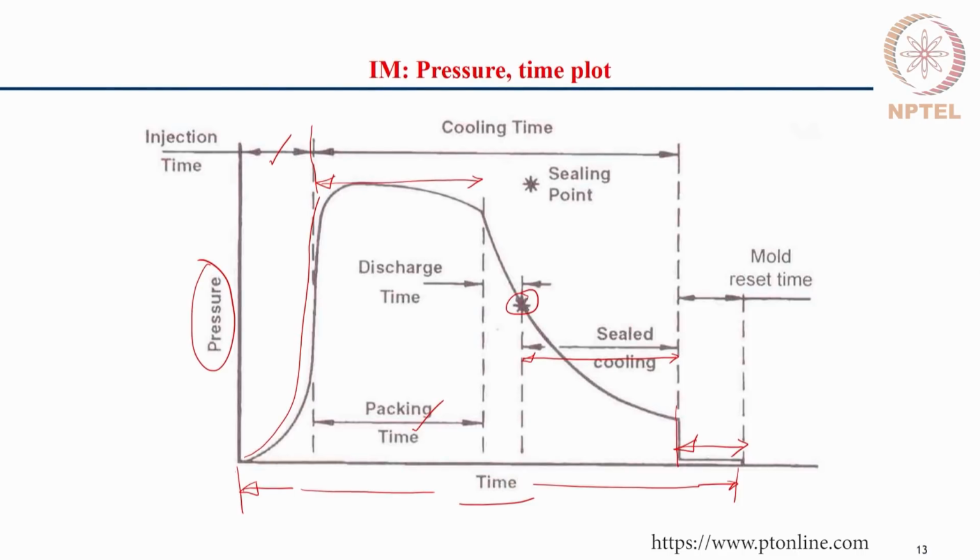So, this graph which shows the injection pressure versus the time is very important from the perspective of optimizing the mold cycle and thereby the cost of the component. This cycle decides the mold filling characteristics and thereby the part quality as well as the cost of the part.